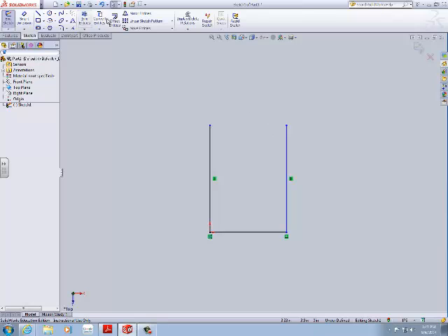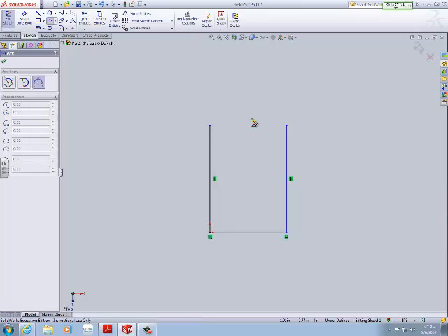And we're going to do an arc. To do an arc, you go... You're in the top plane or the front? Top plane. Yes, you can even see it over here. It's kind of activated, highlighted on top plane. Okay, so we go to a 3-point arc. Under the center point arc, there's the 3-point arc. I'm going to select the end point here, end point here. I'm going to scroll it up until I feel it snaps the center point to that horizontal dashed line.